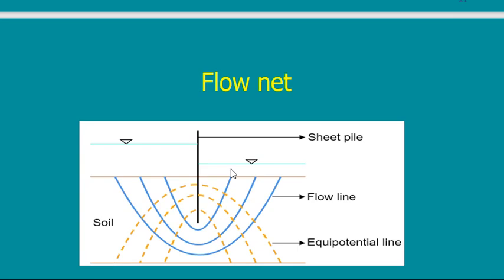The pressure was consumed in the motion from this point to this point. So now it is stable, because the actual pressure at this point is not like the actual pressure at this point. The actual pressure here is the same pressure here minus the pressure that was consumed during the journey of the water. So we ended up here losing some of the pressure.